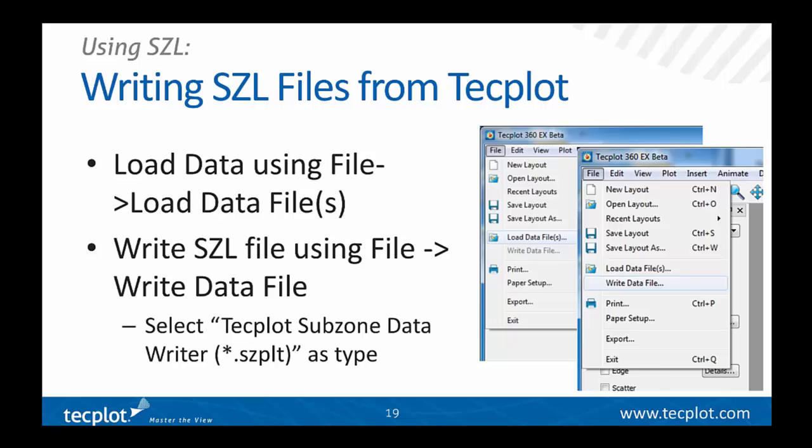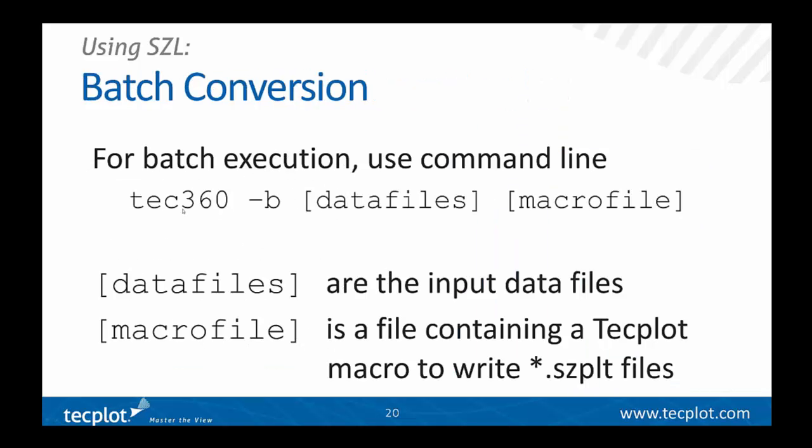If you want to automate that, Tecplot has a batch command capability. So using the command line, you can just say tec360 with a -b.